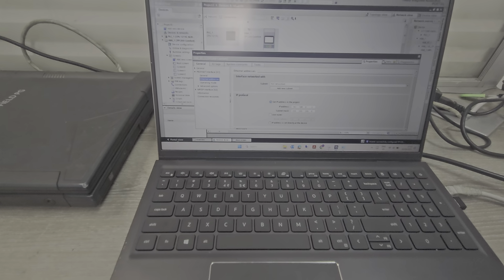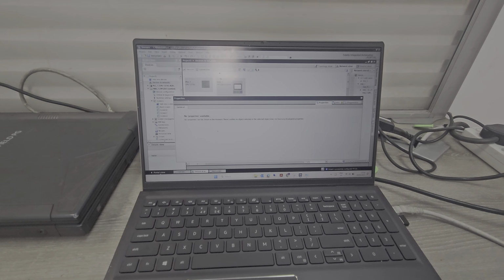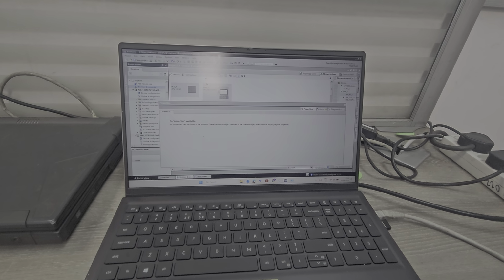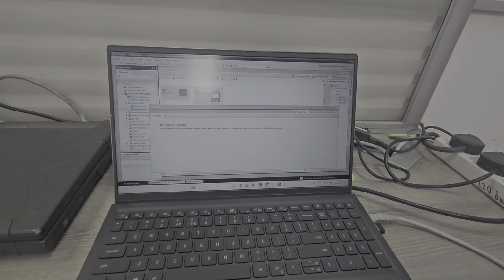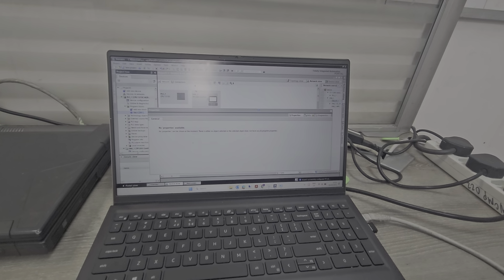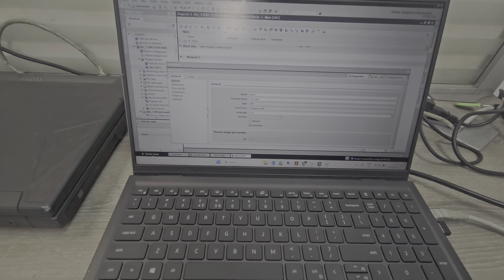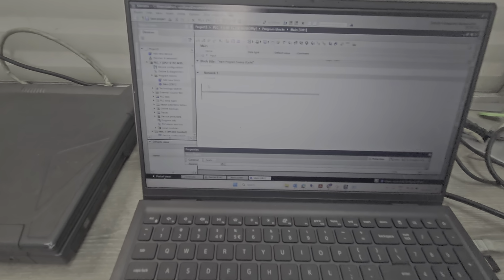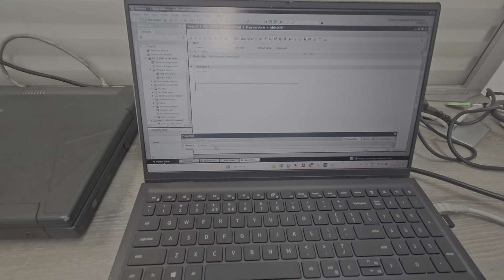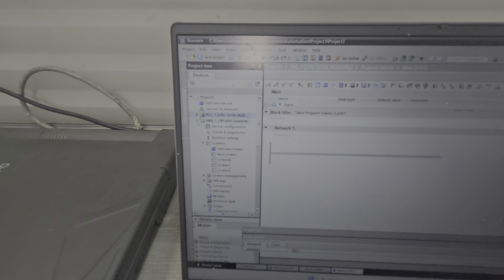And one last thing before we end the session. Once I'm done with this device configuration and the network, I will be able to go to my PLC, and let's say Program blocks, OB1, and in OB1 that's where I can write my programs. I'm just going to minimize this one. That's where you write, whether you're writing ladder logic, or FBD, or statement list. That's where the PLC program will be. And for the HMI, you come there.